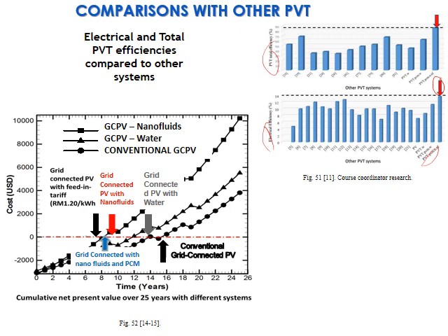Okay, and to see how long it takes for us to return our investment, which we call the payback period, you can see here a comparison between nanofluid, water, and conventional. For conventional, our return back is between 14 to 16 years. When we use water, it's reduced, it becomes less than 12 years. When we use nanofluid, it's talking about 8 years. So you see, this is the term when it's reduced. This means that the system is better and getting better.